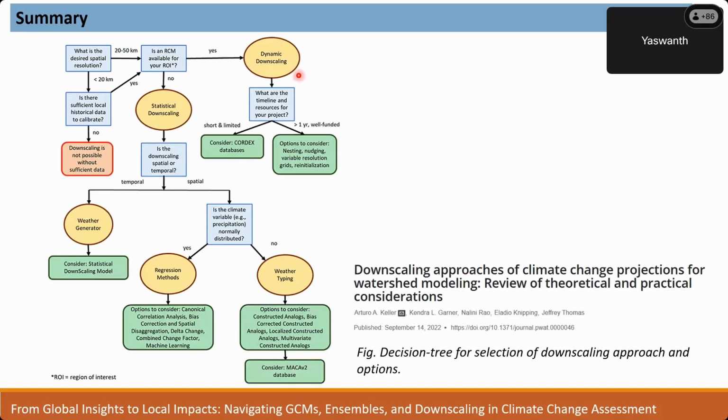So in terms of conditions, we have statistical and dynamical downscaling. If we have the resources for our projects, say well-established computational power and storage capacities, because sometimes the dynamical downscaling outputs need terabytes of capacity to store, and the analysis is much more complex, then we go for dynamical downscaling. Or else we go for statistical downscaling. The downscaling I have discussed here is spatial downscaling, that is, bringing the 100-kilometer resolution to 25-kilometer or 10-kilometer resolution.